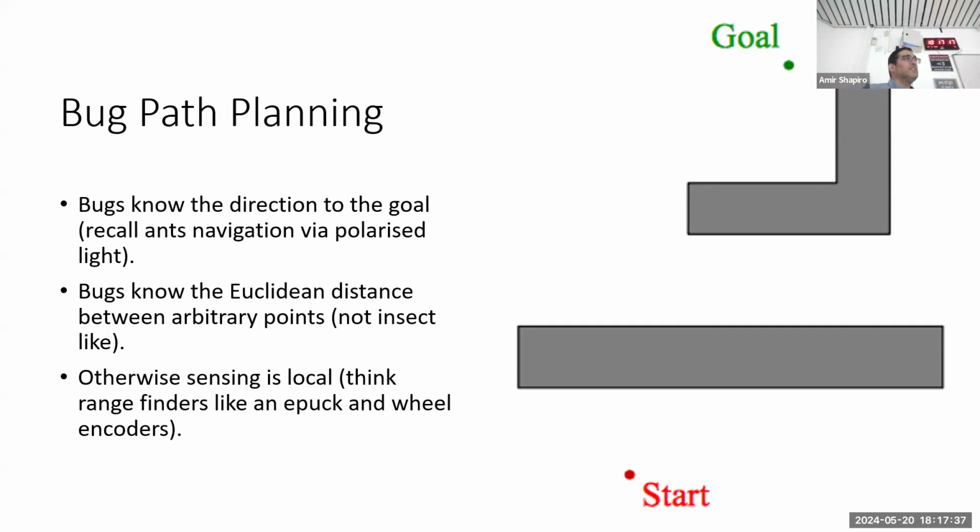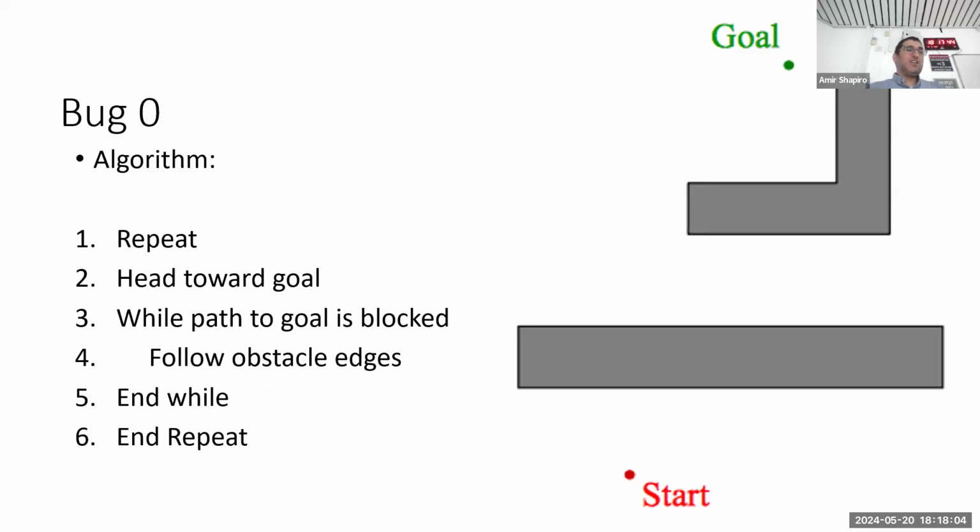We go toward the target and start to collide with the obstacle. And after you pass the obstacle... Yeah. Go around. Go around and fix the time or the distance to go near the obstacle and then go to the goal again. Yeah, you're on the right direction. So, Bug zero